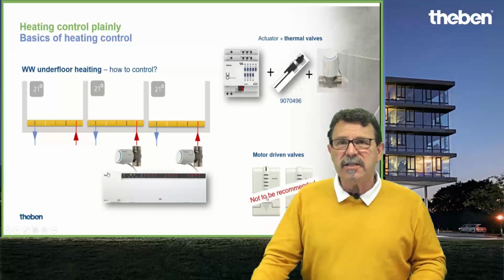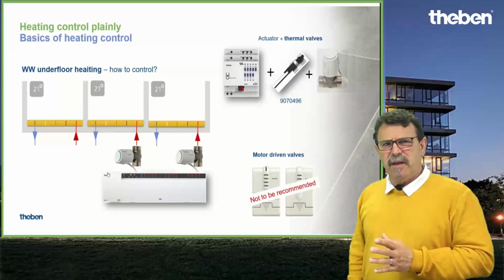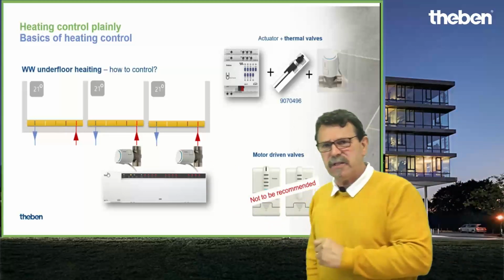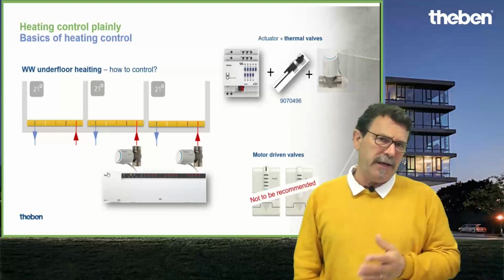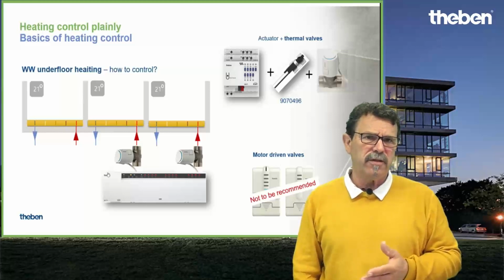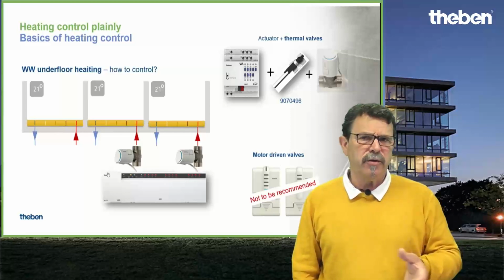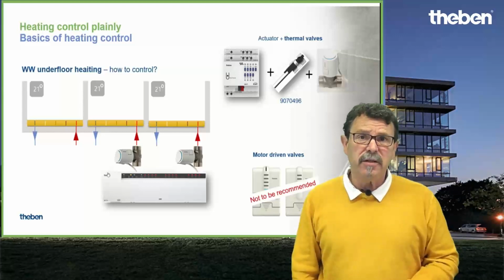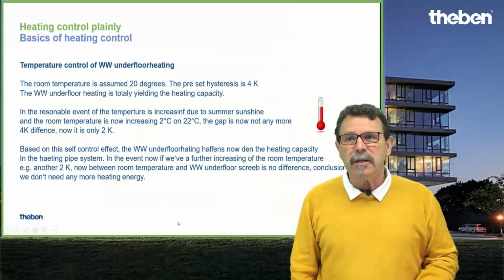In this case, for underfloor heating, as I mentioned, we recommend these thermal valves. Motor-driven valves, okay. The efficiency is not better, so if you use motor-driven valves for underfloor heating, it is not more precise in comparison to a thermal valve. That's just a matter of price. Motor-driven valves are more expensive. If you want to invest, always welcome. But if you invest, then invest in our Theben motor-driven valves, and then you will have a reasonable result.